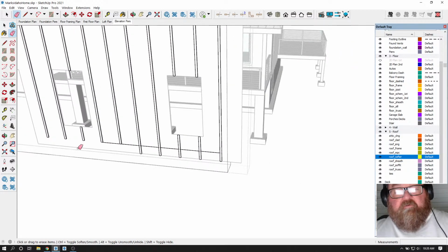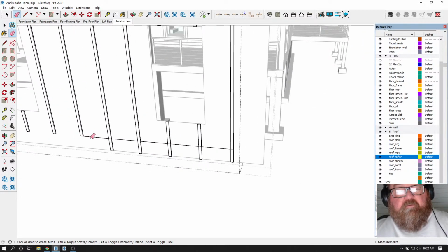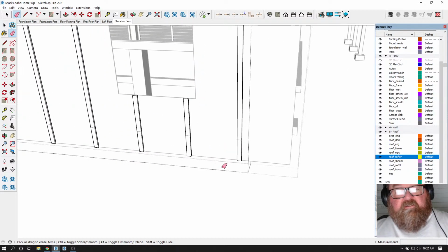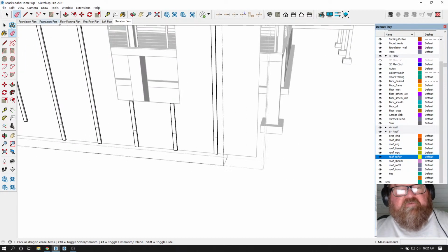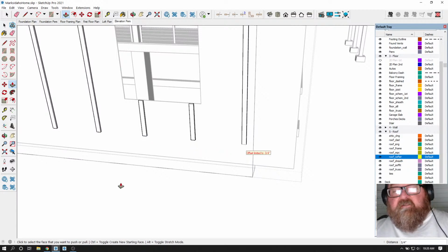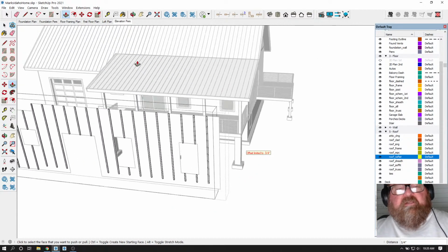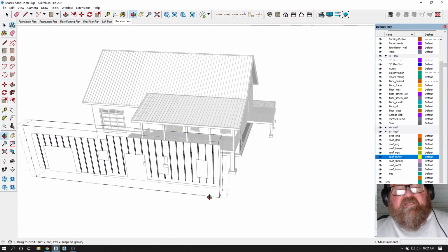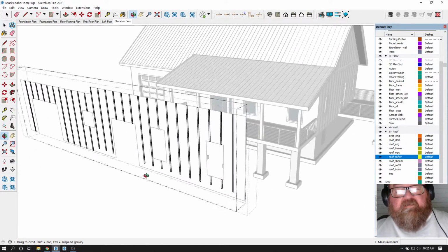But you can either stop the siding there too, or it's thin enough to where you can run it down behind the band if you want to. It depends on when you do the porch framing. I actually like to put flashing behind the porch band and do the porch band and then set the siding on top of it. That way, if you ever need to change the siding out, it's not behind it.